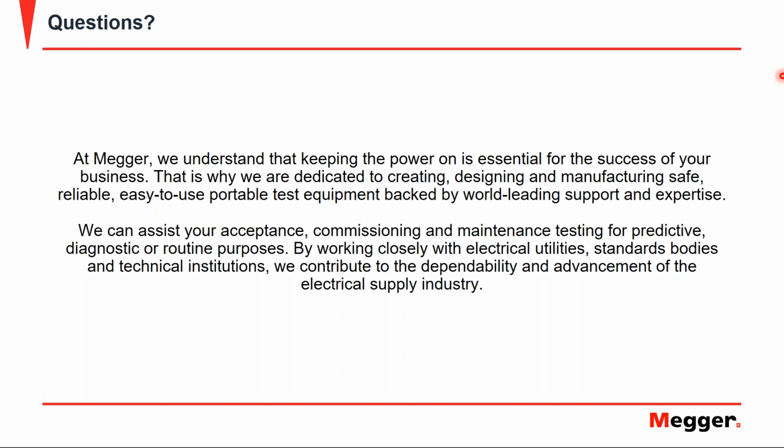When we're taking partial discharge measurements on a cable, it's important that we're able to isolate both ends and air insulate each end of the cable. I understand that there are situations where it may be difficult to isolate a cable from a piece of equipment, but if the cable is not properly isolated, that brings its own set of challenges.